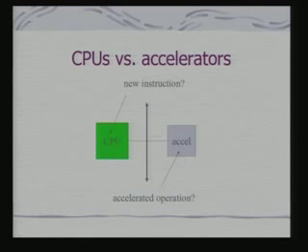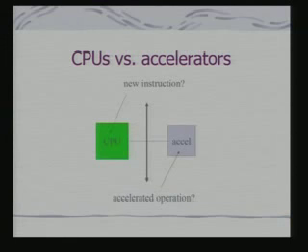If you go back again to the camera example, we found that DCT was the bottleneck. So we might like to use this FPGA block to implement DCT to remove that bottleneck. We are not modifying the CPU in any sense, but we are implementing a special functional unit, and many times we refer to that as an accelerator.